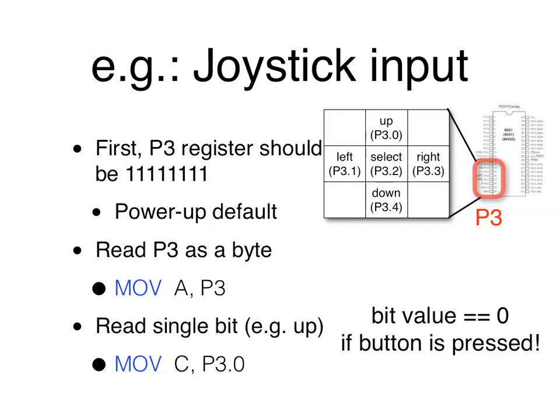This is an example where you have a joystick. You may have seen these, right? It's a small device. You could push it up, down, left, right, and then center, right? So there are 5 possible switches in here, but each time you can do at most one of them, and it's controlled using just one little stick, depending on the direction. You can view a joystick as 5 switches in one package, and you can choose one of them at a time. And this could be done using a GPIO.